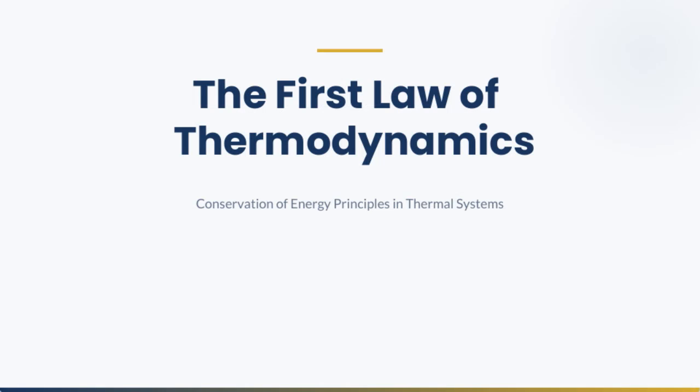Today, we're diving into the conservation of energy principles in thermal systems, focusing on the first law of thermodynamics. This law essentially states that energy cannot be created or destroyed, only transformed from one form to another. In the context of thermal systems, this means that any heat added to or removed from a system, along with work done on or by the system, must be accounted for as a change in the system's internal energy. It's a fundamental principle that helps us analyze and design efficient energy systems.